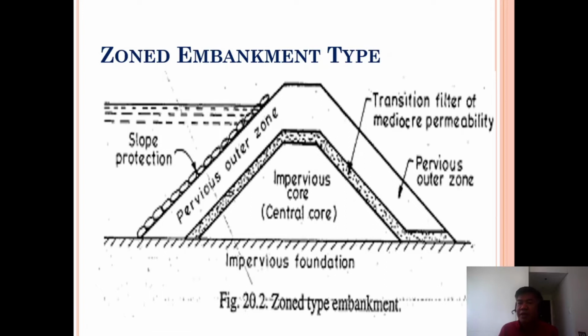Number one purpose of having those could be to reduce the pressure of seepage. That's why in analyzing different types of embankments, of course, compared to the homogeneous, this one will incur higher cost because of the different materials in this cross section. But if the homogeneous will fail to meet the requirement, then the zoned embankment could be one of the solutions. So you just have it there.